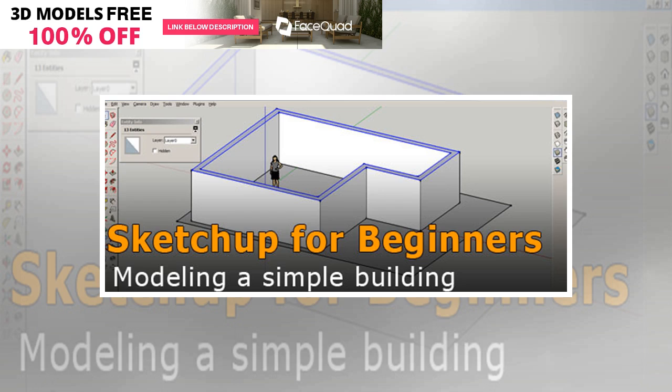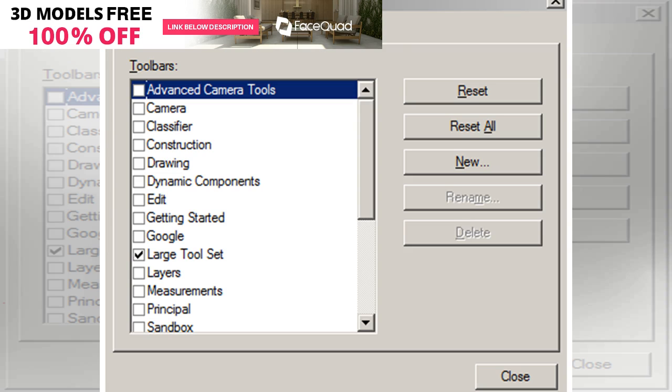So, you have typed the correct dimension of the previously measured wall. Click Yes in the pop-up to confirm scaling of the entire model, and now you have your floor plan in real-world scale. To check this, measure again. You must obtain the proper dimension.